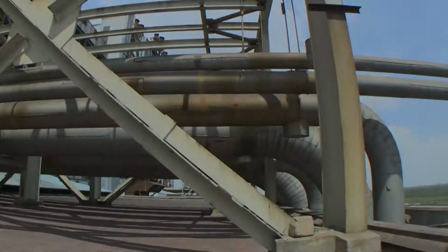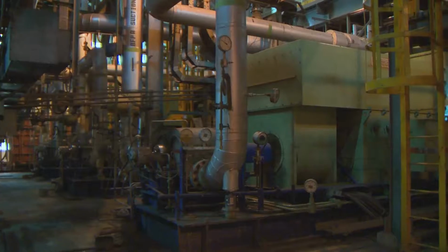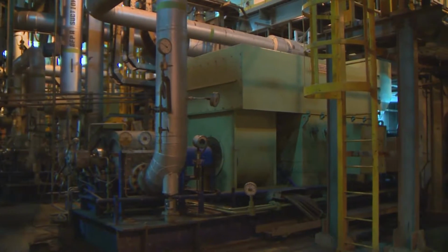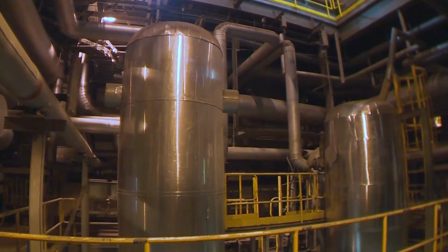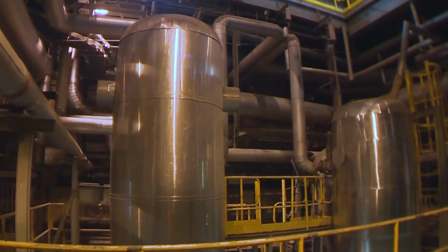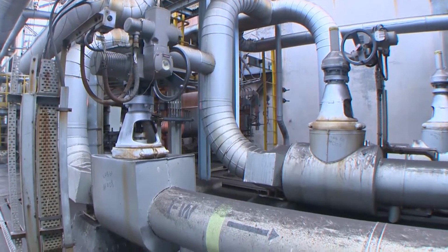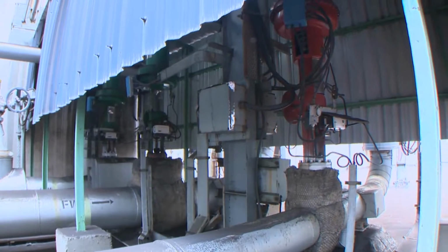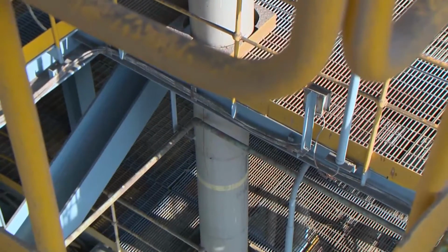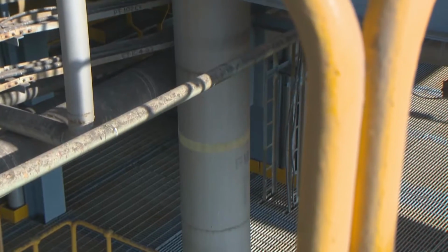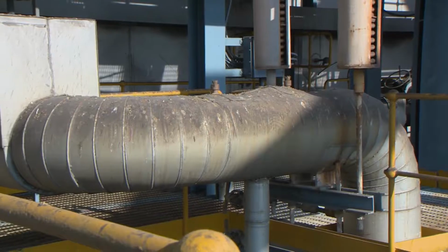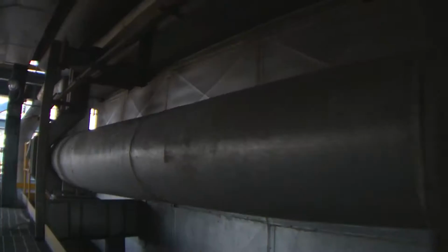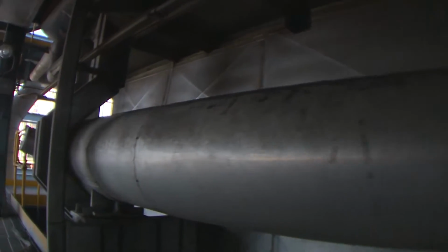Water and steam cycle. Boiler feed pump supplies feed water to boiler through high-pressure heaters with sufficient pressure and temperature. The feed water flow is regulated by pneumatically operated automatic control valves. Then the feed water goes to economizer, which improves the boiler efficiency by extracting heat from exit flue gas and thereby increases the feed water temperature.